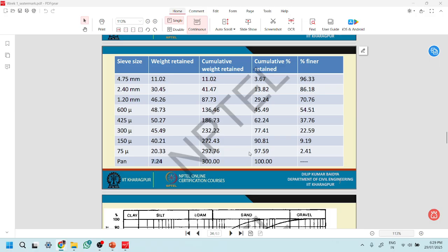I think that the soil that you are using, you can classify based on this IS classification, and then there must be a range of particles that you are using for soil stabilization. I don't think another particle size distribution is to be done after amending with fly ash, because it's kind of a geopolymerization. Are you working in geopolymerization?